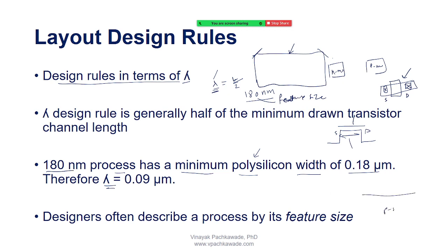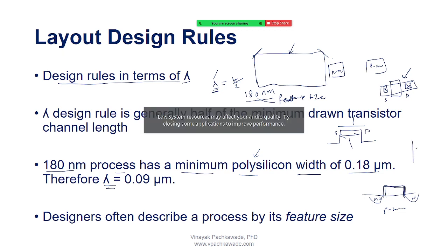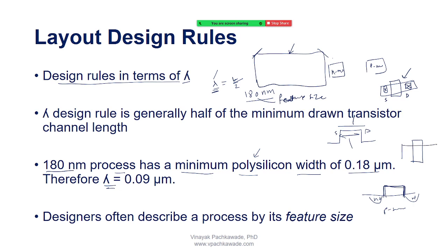See, I have a P substrate. When did I fabricate the source and drain regions initially, or did I fabricate the gate initially? Gate first. Good. Gates will always be fabricated before the active diffusion regions. Why? I am drawing a cross-sectional view. The top view would be like this. You have this active area, and then this is the substrate.